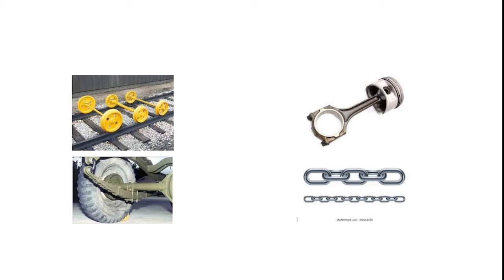The fatigue always occurs with respect to continuous or cyclic loading. So how the material behaves with respect to cyclic loading is an important study. The fatigue fracture is caused by the propagation of cracks that initiate at a single point or at a few points, which may be laterally dispersed on the material surface.